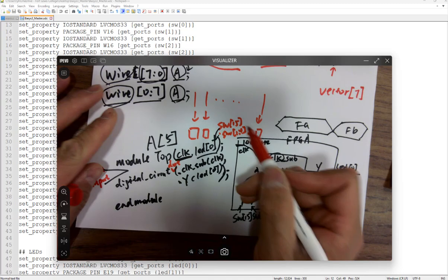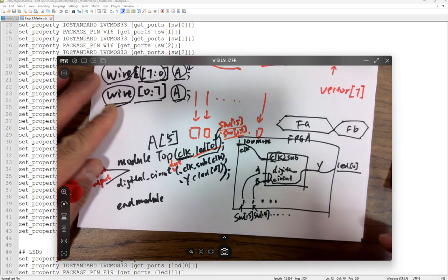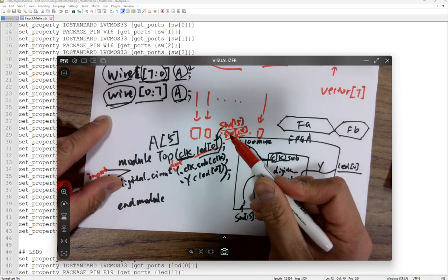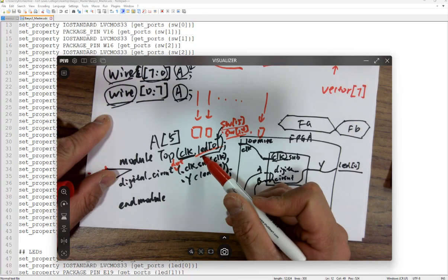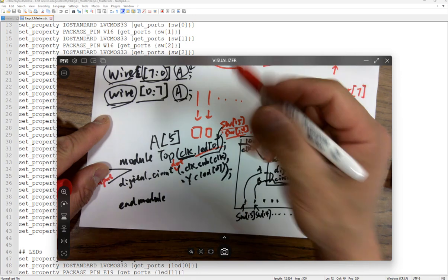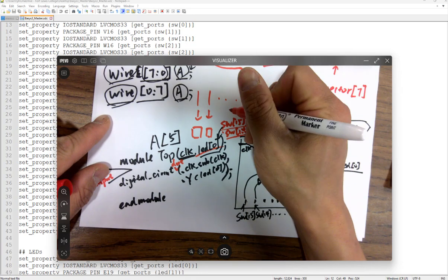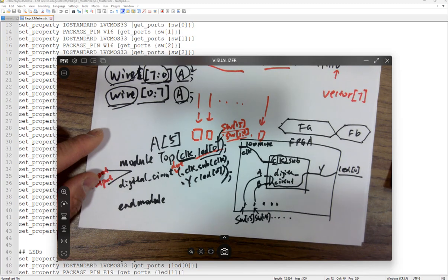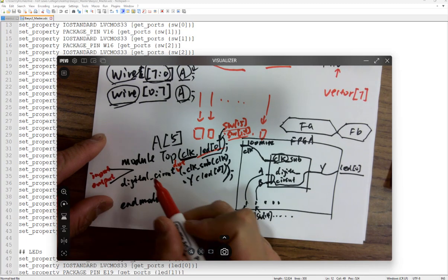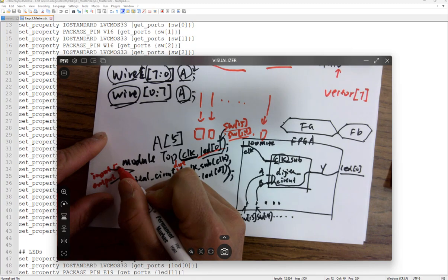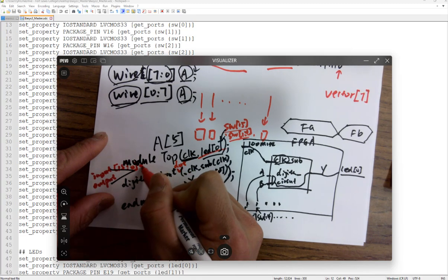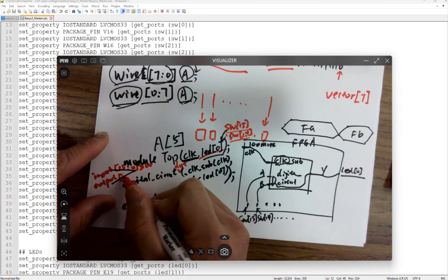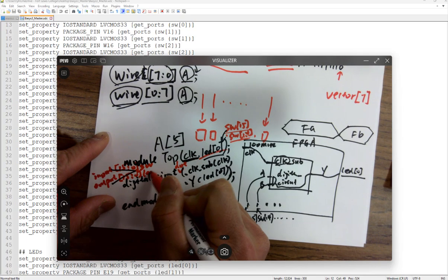A lot of times we don't really do them individually, just make it simple. Sometimes it reports errors. It's a bit inconsistent. So a lot of times since we know we have all the LEDs and switches available, we usually just declare everything. For example, input is 15 to 0 SW. Output is 15 to 0 LED.